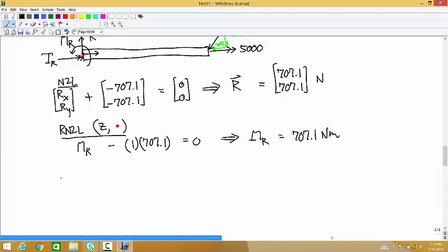Now we'll do the rotational version of Newton's second law about the x-axis. As an about point, let's think of the center line of the beam extending all the way down the length of the beam. That's not going to come up, because all the moments happening in the x direction are couples, so they don't depend on the about point.